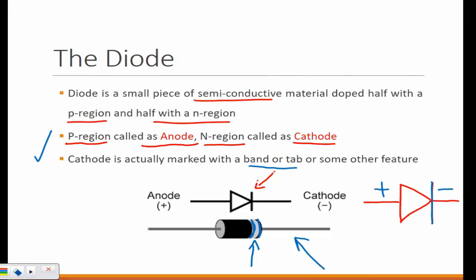It's just a mark. It doesn't represent anything. Depends on the manufacturer. Someone will go with a silver color mark. Some use black. Because there is another diode that you will see. The whole diode will be orange color. But there is going to be a black color mark on one side. That means that black color mark is the cathode. If everything looks good, your circuit is not working as it's supposed to, probably you put the diode backwards.